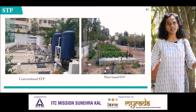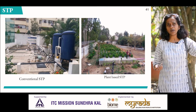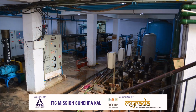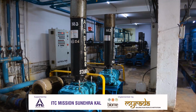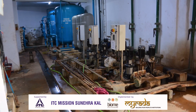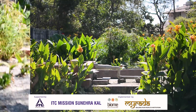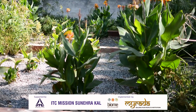In most layouts, however, there is a common STP, and wastewater, which includes black water from your kitchens and from your toilets, as well as your bath water and washing machine water, goes to a common STP, a sewage treatment plant. Sewage treatment plants can be of multiple types, some which are electromechanical. That means they need electricity to keep running and there are moving parts. They use technologies like activated sludge process and sequential batch reactors to treat the water. You could also have nature-based STPs which rely on soil and plants to treat the water. But the final output is treated water, and it is our responsibility to make sure that treated water is reused.